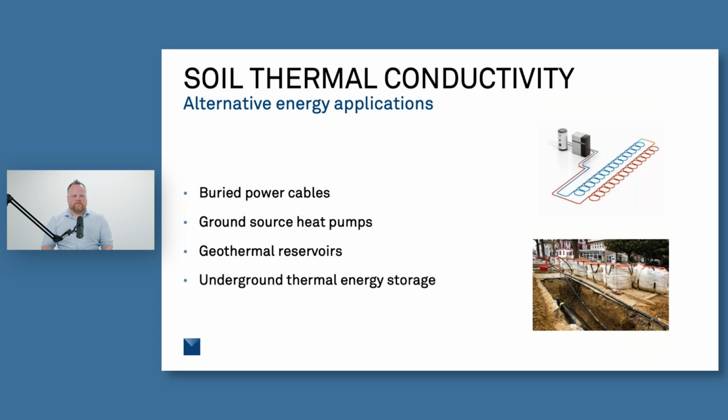There's been a few stories in the news the past several years where the thermal conductivity has not been properly considered, and those cables heat up too much, the shielding melts, and then you get damage to cables, you get loss of power to customers, and it's very costly to fix. So making sure that that's really understood and that you're using materials that can handle that kind of heat load is critical.